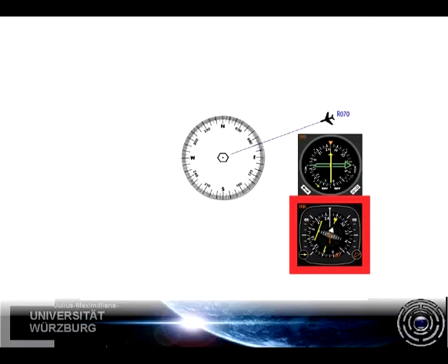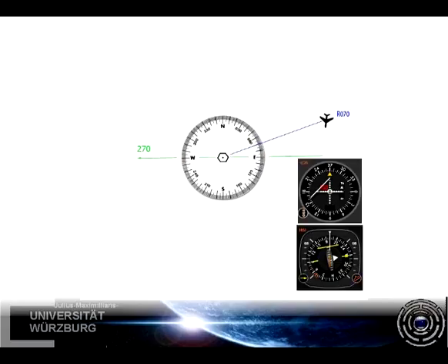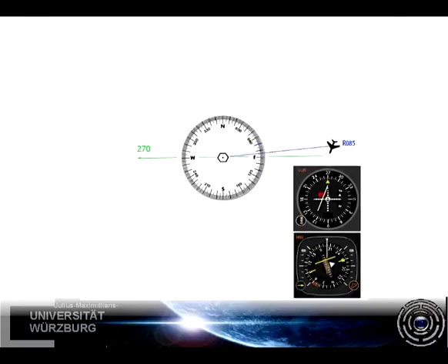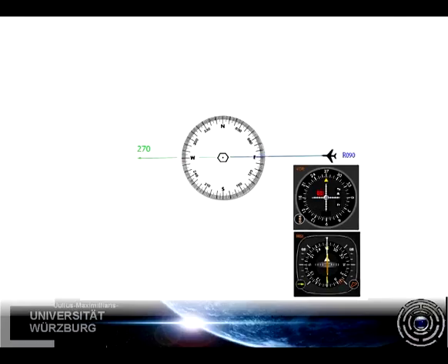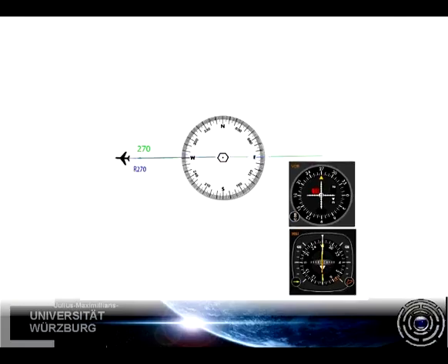Let us take a look how this maneuver would be done with an HSI. The HSI is basically a CDI glued on a heading indicator. The yellow arrow represents the course that we wish to fly over the station at. The deviation bar is the displaced part of that yellow arrow. As we approach the desired course, the deviation bar closens to the center, just like the one from the CDI. This is what it looks like when established on course, on the to side of the station. And that is the HSI after crossing the VOR.